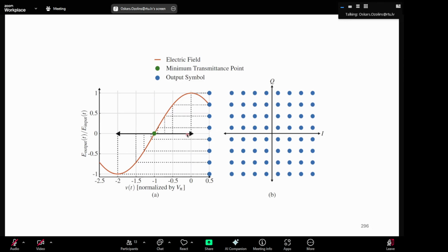Here we see, for example, the I signal. In this case there are 1, 2, 3, 4, 5, 6, 7, 8 levels. So PAM8 is used to generate 64 QAM. You have 4 times the symbols of 16 QAM. You see here are 16 points.